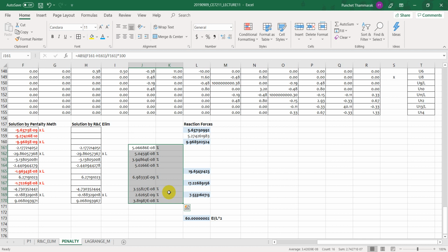If it is a constant cross-section bar but you discretize somewhere into a very small L. For example, if L is 1 in 100 of the entire length, whereas the nearby element is 0.99 L, the stiffness you obtain from two members is approximately 100 times different. It could get worse and worse as you have more and more difference in size of the member.